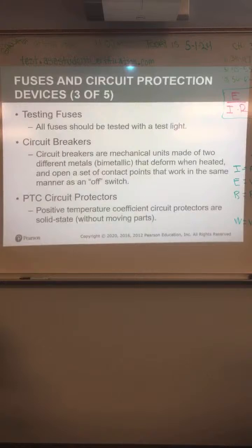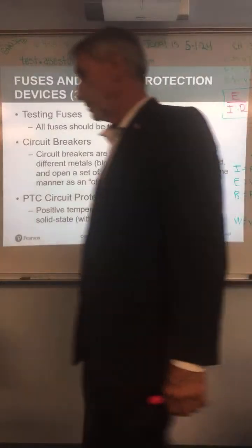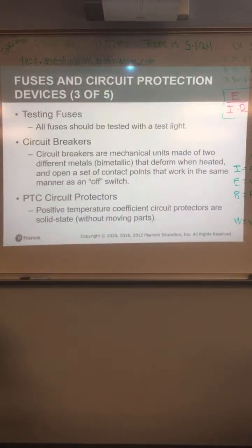Most fuses have test points on them. You can test them with a test light. We looked at this before, did we, or not? Yeah. If you look at these fuses here, they have two little test points on them. You just put the test light on one side, and the other side, you got power on both sides, the fuse is good. If it lights here and not here, the fuse is bad, okay?